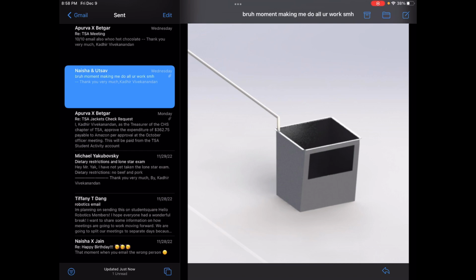It might look like the hole is unnecessarily large, but the hole is actually designed to match the flow rate of the downspout and all the water that can potentially go in. So even in the worst case scenario with extreme rains, we will be safe because this cutout can carry as much water out as the downspout can carry.